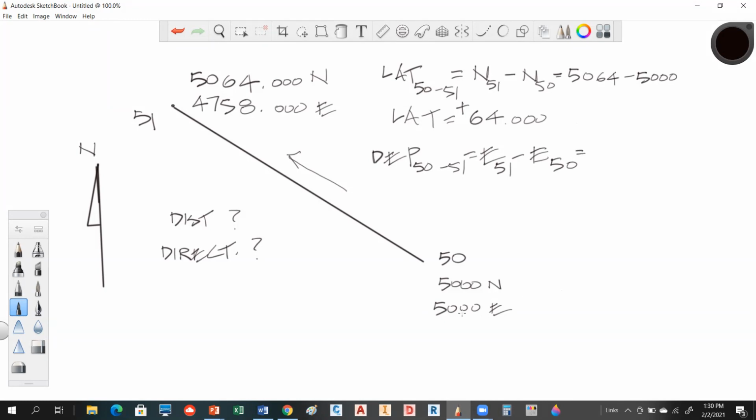So the easting is 4758 minus 5,000. So notice we get a negative 242.